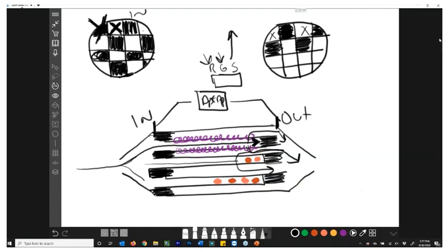So if we're talking about a standard DPF-DP, our key on engine off voltage is going to be somewhere around 6 to 8 tenths of a volt. And then a full, completely stopped up DPF, couldn't be any more stopped up, you're going to be somewhere around 4.3 to 4.5 volts. But that's severe, severe, severe. Vehicle probably won't even run if you reach 4.3 to 4.5. So as these chambers start filling up with soot and ash, our signal voltage starts to go up. And it goes up to the point where the ECM realizes, my pressure is really high, and it's because my chambers are getting full of soot and ash.